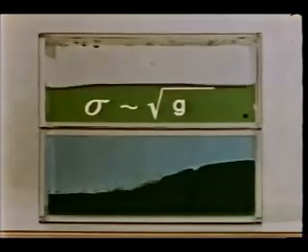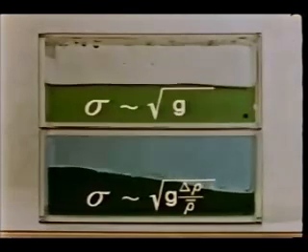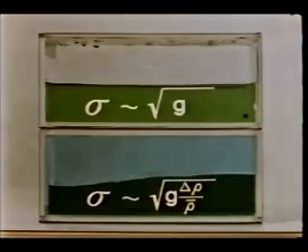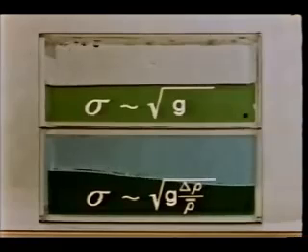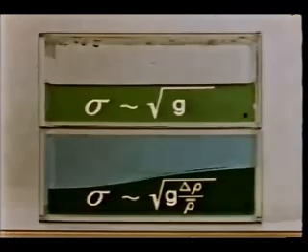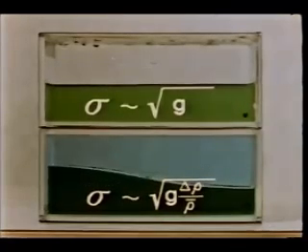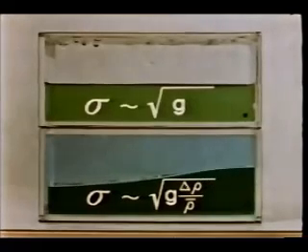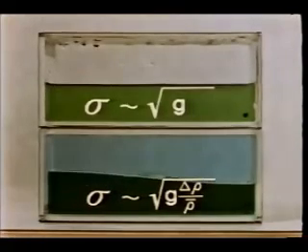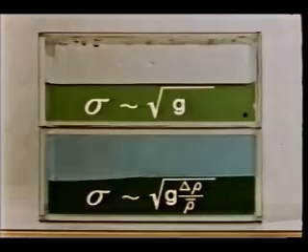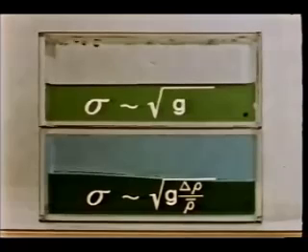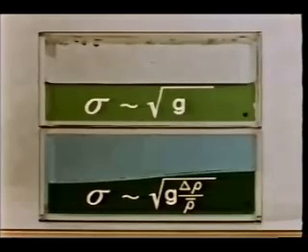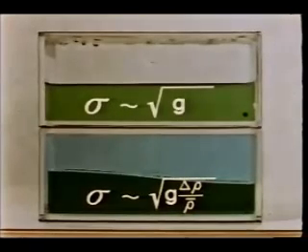The restoring force for water waves is the gravitational force G, but for internal waves, the restoring force is G multiplied by the small number delta rho over rho bar, where delta rho is the density difference between the liquids and rho bar is the average density. The quantity delta rho over rho bar G is sometimes called modified gravity. Of course, even in the water wave case, the G in the formula for the wave frequency should be multiplied by delta rho over rho bar. But here, delta rho over rho bar is very close to 1.